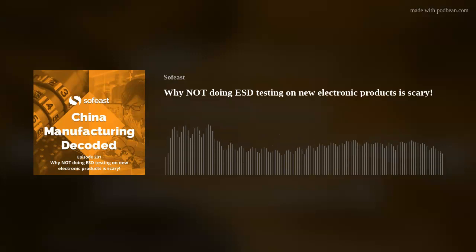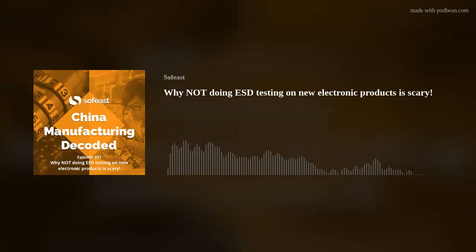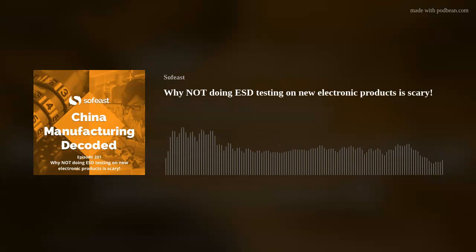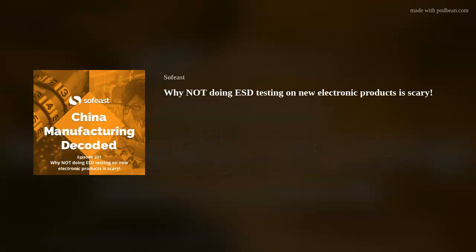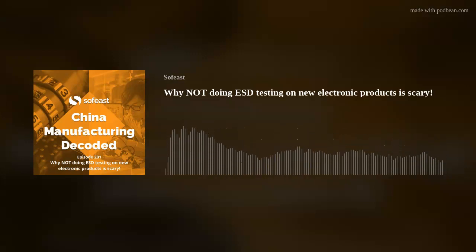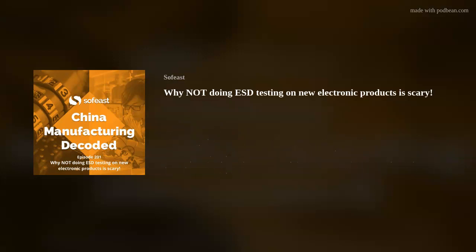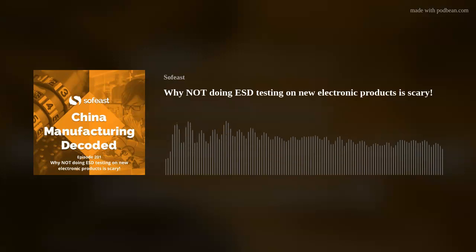Okay, good. So let's talk a little bit then. We know the sorts of tests that you're suggesting, and that's very clear. But just before we move on from tests, if you're engaging a testing lab in China, India, could be anywhere, in Europe, to do testing, and they're going to test for ESD resistance, would most labs be able to do this pretty easily? Yes. ESD testing actually is not too difficult anymore, and the test equipment is not so expensive. I think you can invest anywhere from 10,000 USD to 20,000 USD, depending on how many different kinds of equipment you want, the capability of testing all at the same time.